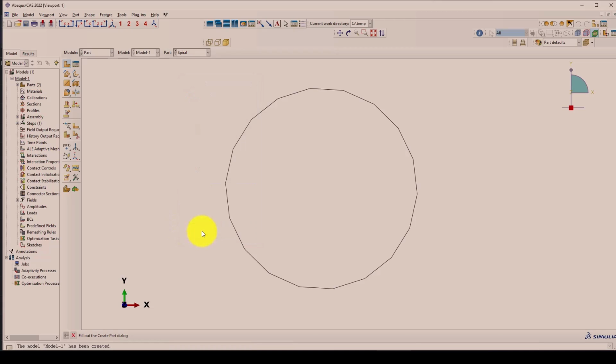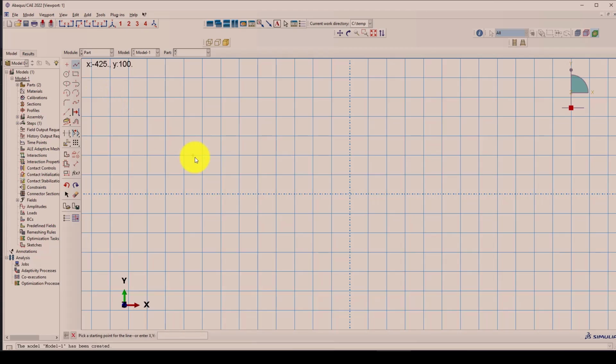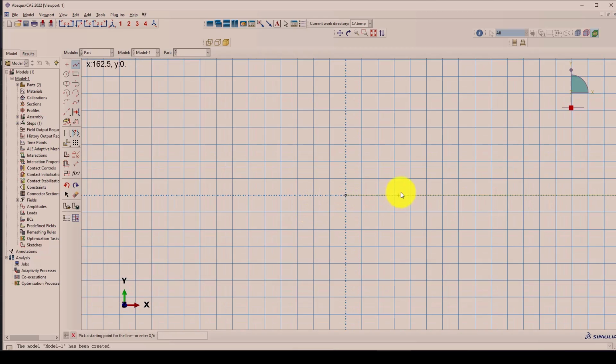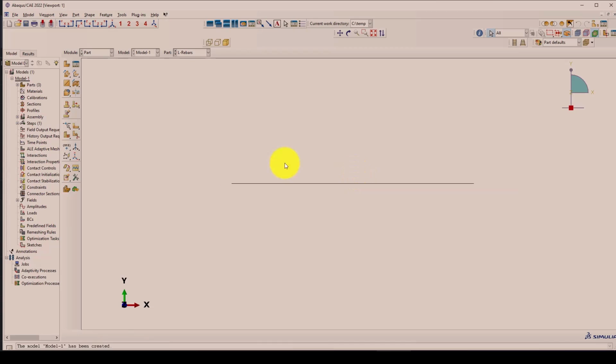This time I'm going to add the longitudinal rebar. This is also using wire, and I can use 0 0. I want to give, let's suppose, 1 centimeter cover at the bottom and the top. So that becomes 1980. So this is it, and we finished this part.